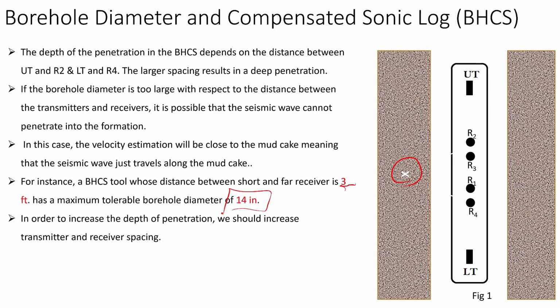So if the borehole diameter is greater than that, it is possible that the seismic wave cannot penetrate into the formation, and as a result, we are not able to measure the seismic travel time in the formation. So in other words, if we deal with a borehole with larger diameter, definitely we have to make sure that the distance between the receivers is large enough so they can measure the seismic travel time in the formation.